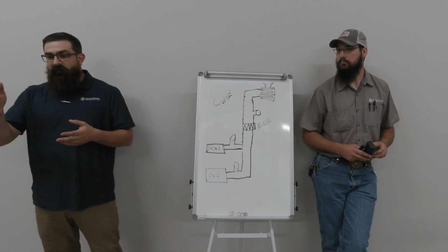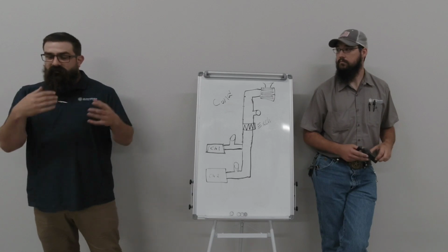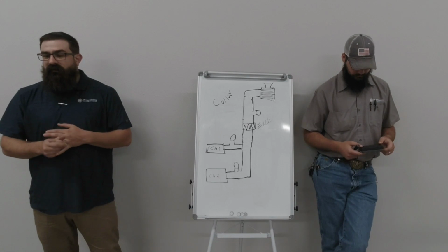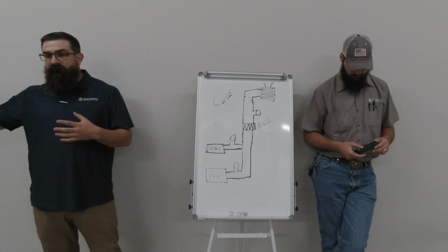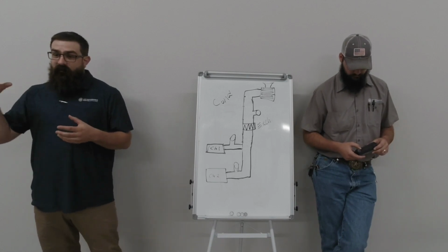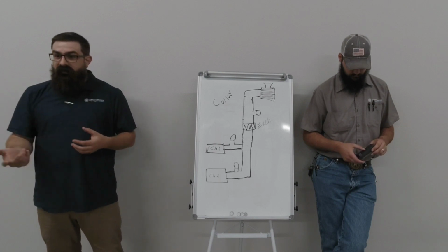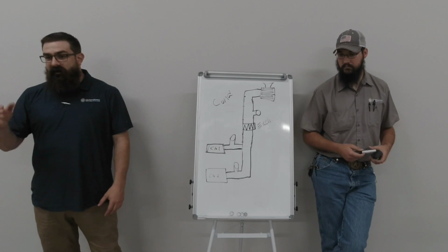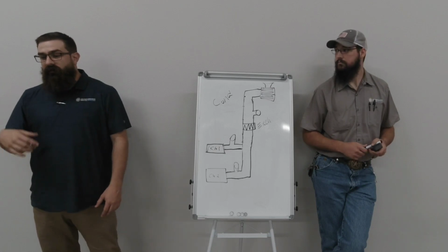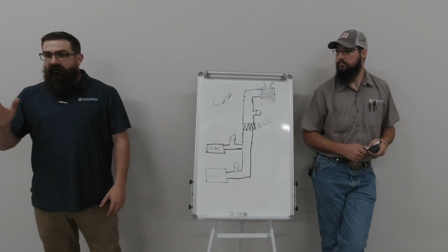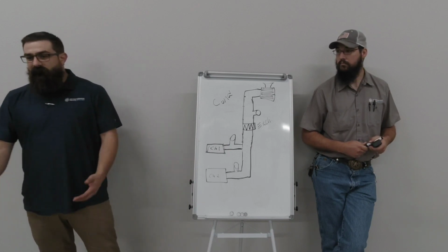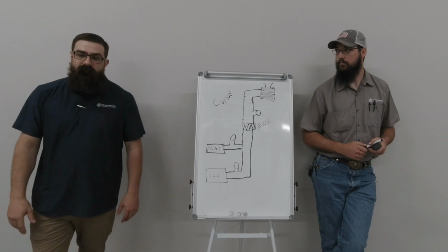So the slower something goes across that coil, the more chance it has to draw heat out of it, right? That's how we can do things with airflow. We can reduce airflow across a coil to give the air more time to cool down. So if we need to dehumidify and we have a chilled water system, we'll slow down the fan speed and drive that coil all the way open, so it's cooling and the air is slowed down across it, giving it more time on the coil to pull moisture out. And then when we're not dehumidifying, we can ramp it back up.